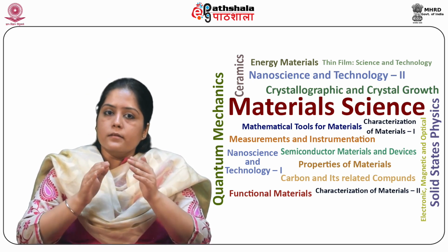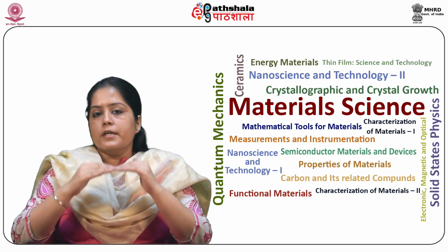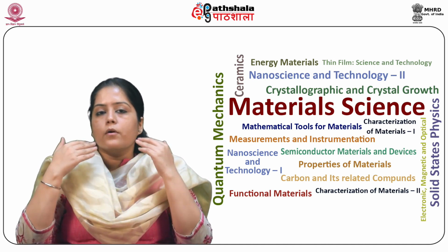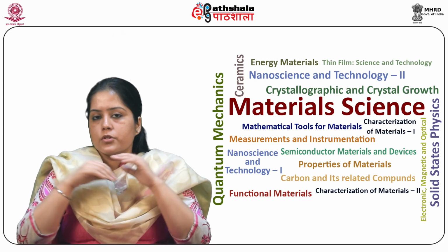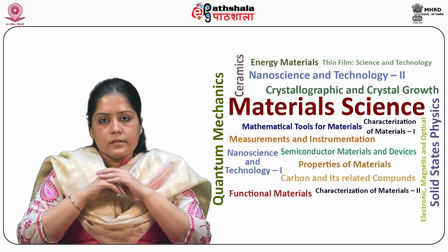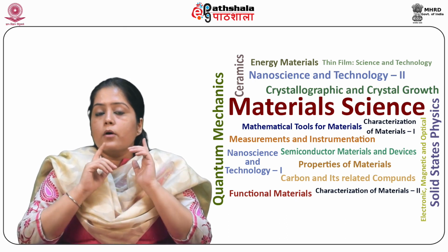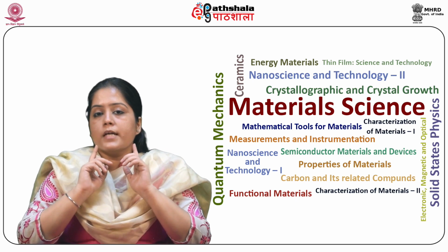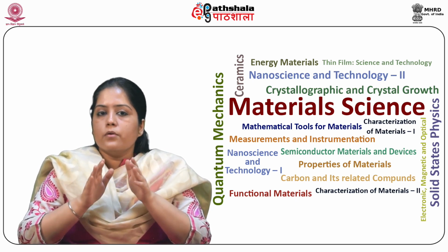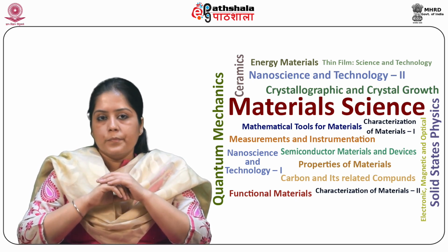The silicon is periodically poured from the furnace and blown with oxygen or an oxygen-chlorine mixture, and finally it is solidified. The produced silicon is about 98 to 99% pure, with major impurities like iron and aluminium.